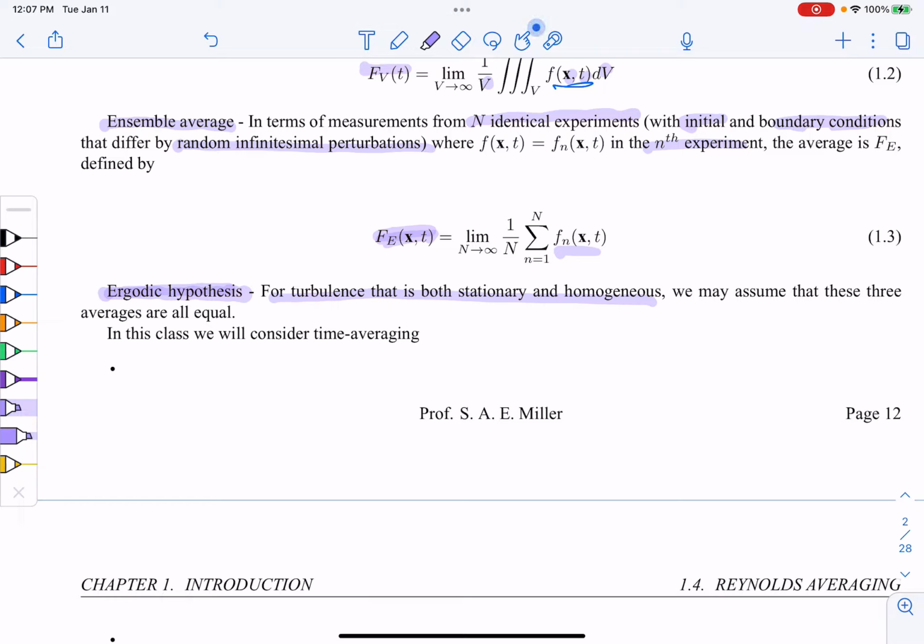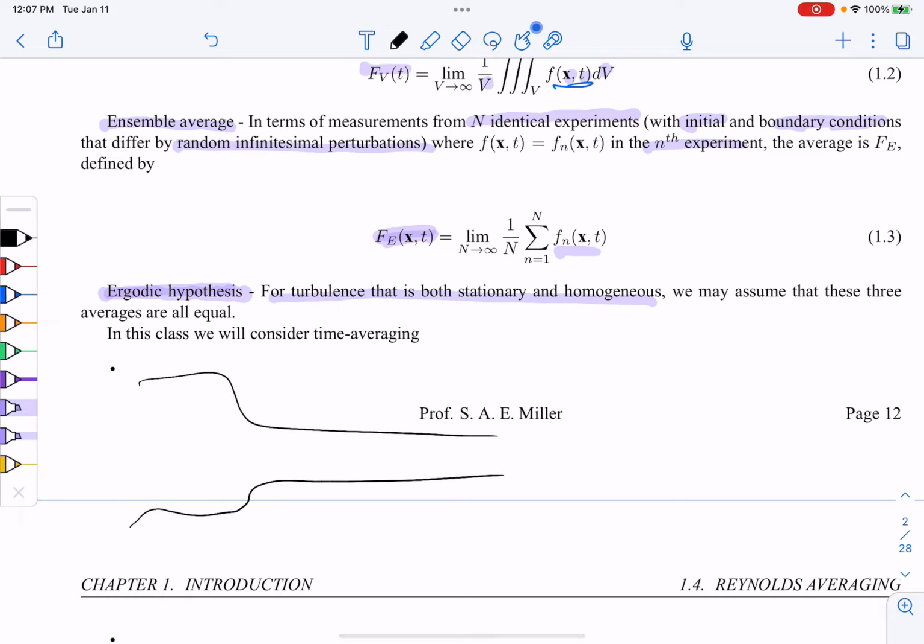So say you are in a wind tunnel, and there's a contraction section. Here's your test section. And you might have a grid here, which is a honeycomb grid. Downstream of the honeycomb, that turbulence quickly decays, and after maybe 10 length scales of the honeycomb diameter it becomes homogenized. And that's how, in practice, a lot of people remove turbulence in these types of tunnels.